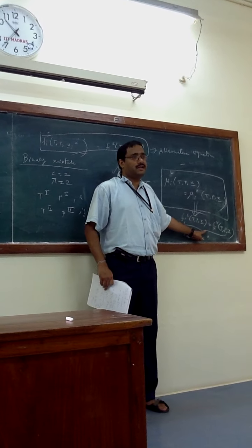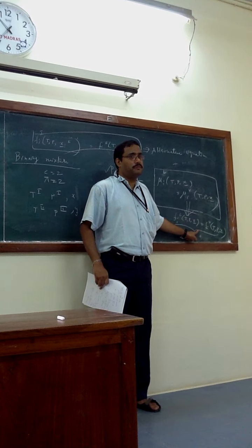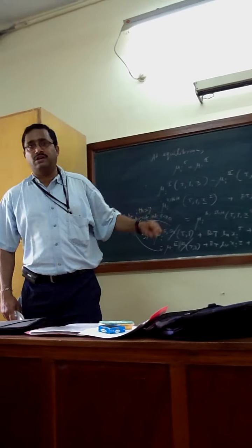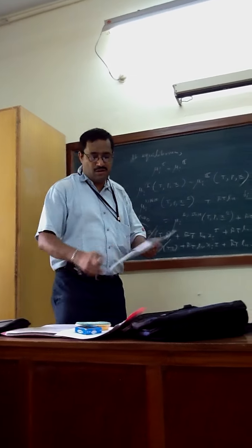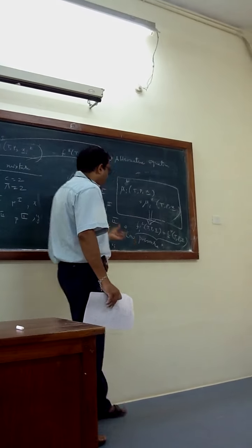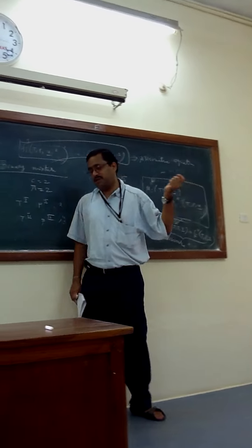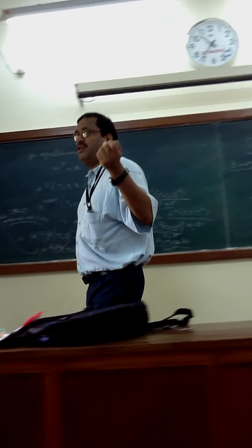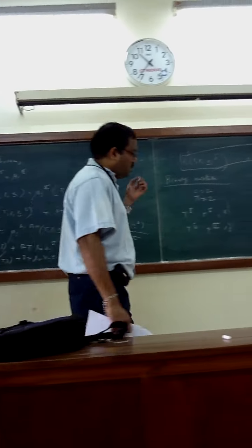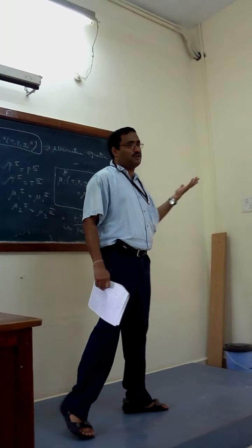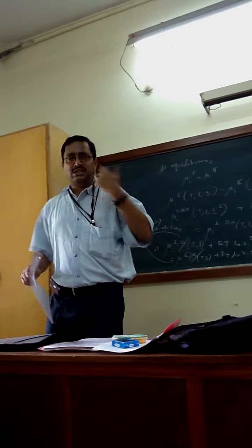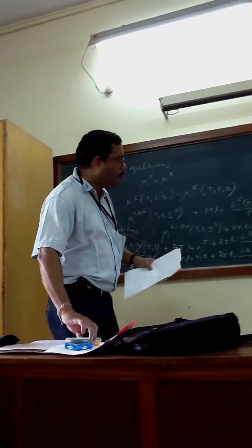So I derive Raoult's law from this. Raoult's law is a consequence of vapor liquid equilibrium. I derive Raoult's law from f i L equals f i V. So if I derive a low pressure situation, the first assumption in Raoult's law is that it is valid for low pressure, both in the liquid phase and the vapor phase. Otherwise you cannot have Raoult's law. So let's look at how we can establish or develop Raoult's law.